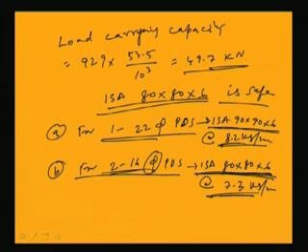That means we can make the section economic. Here it is 8.2 kg per meter, here it is 7.3 kg per meter. So the section weight can be reduced by the use of reduced diameter of rivets, by the use of more number of rivets. In place of a single rivet, if we increase to 2 rivets, then we can get a little economy in terms of weight of the section. So far we have discussed only axially compressive load.